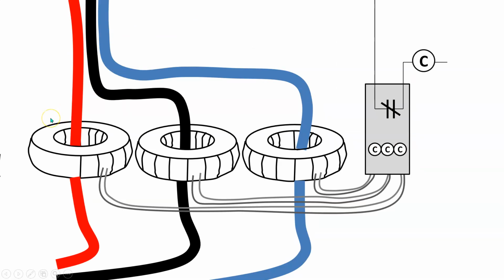Okay, and then we have current transformers. Current transformers, you'll start to learn about, maybe you're learning about them in second year code. Pretty much they're a sensing device that a conductor is fed through. So here's your line 1, line 2, line 3, and they're fed through these little donut-shaped things, which is pretty much just a coil of wire. These coils of wire are going to be picking up the magnetic field based on the current traveling through these conductors, and it's going to send a certain amount of current to your current transformer.